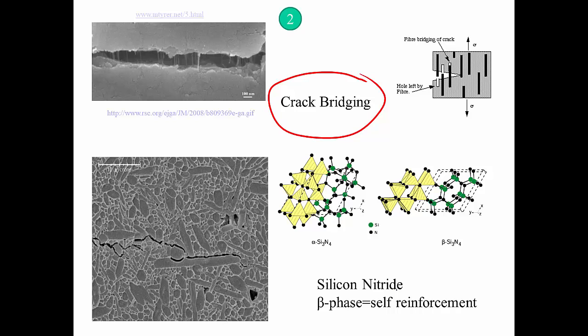at the crack tip. So remember that the stresses at the crack tip in general are proportional to the stress intensity factor, and that would be your F sigma square root of pi a. So that is for a fully open crack. If you have these fibers or microstructural elements that connect the two sides, the intensity that is felt by the crack tip from the same stress is actually reduced, because these connections provide for the support.